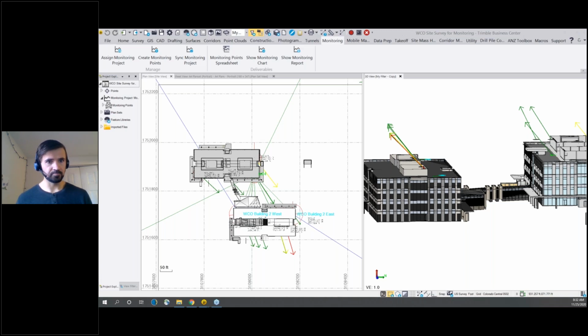Dylan asked a question. Is it advised to create a new Trimble Access job each time points are observed in the field? So, question about Trimble Access monitoring. It depends on what the job is and what the purpose is. If it's the same job, let's say I'm measuring the same structure every time, you can do both. You can create a new job, or you can use the same job and monitor essentially another set of rounds. It really depends on your workflow.